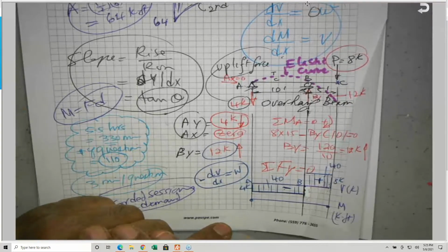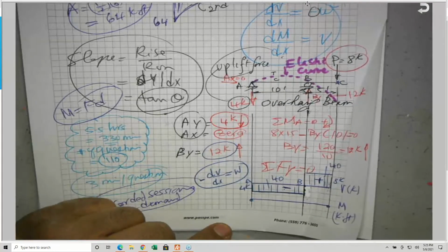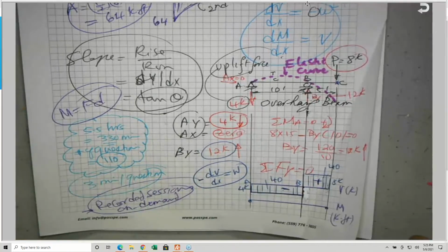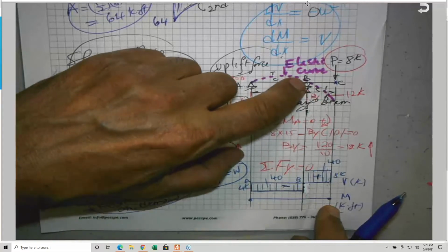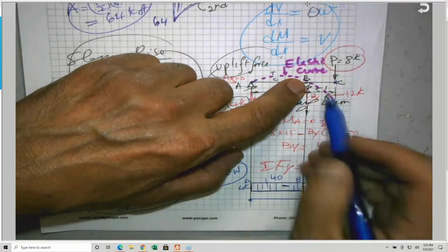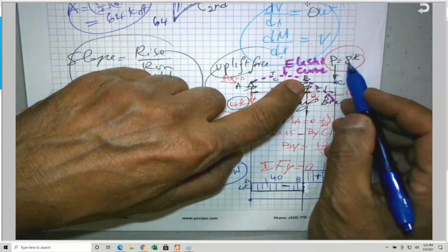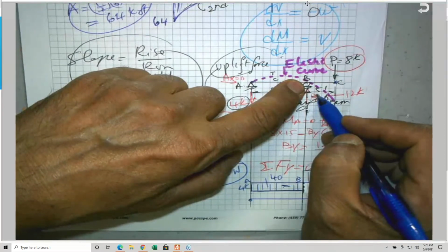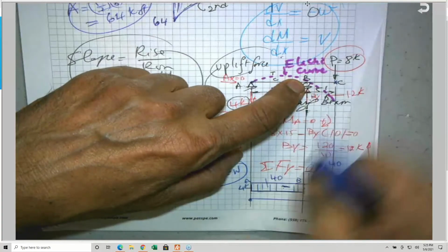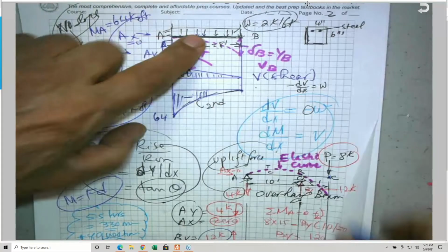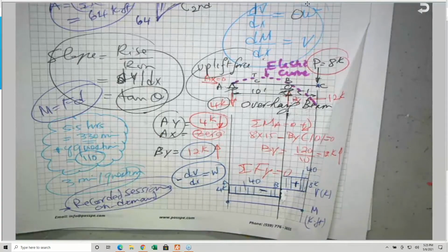So if you look to the bending moment, I know 2 key points. I know the bending moment is negative from the beginning to the end because of the elastic curve. If you don't know the shape of the elastic curve, you're still able to find it, because I can look to this point B, and what will be the bending moment here? Again, either from right or from left. Right is much easier. 8 times 5 is 40, and it's just going to bring the beam down, like the cantilever. But this is a distributed load, this is a constant, so it is negative, and it is linear.